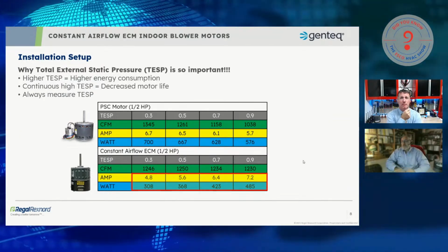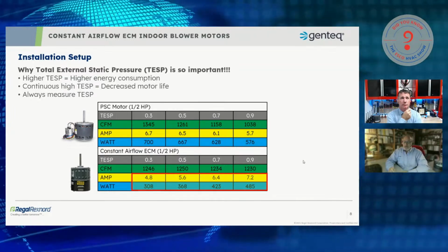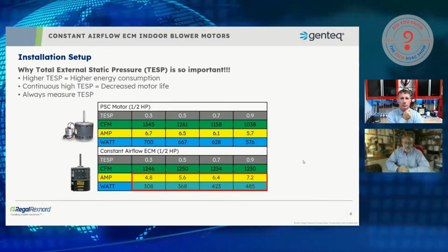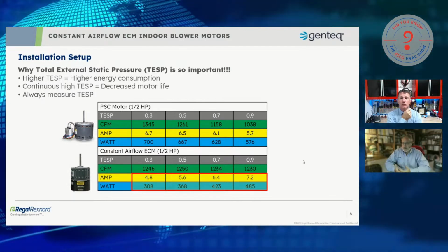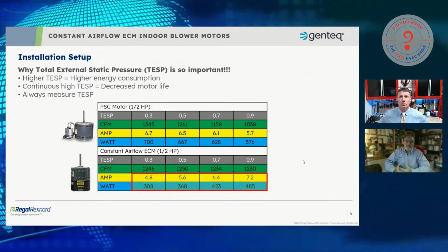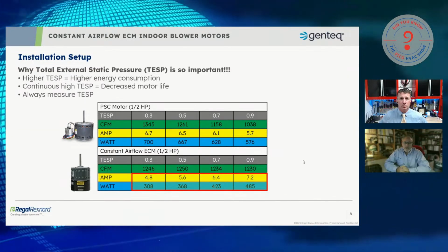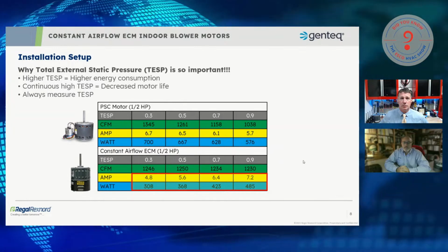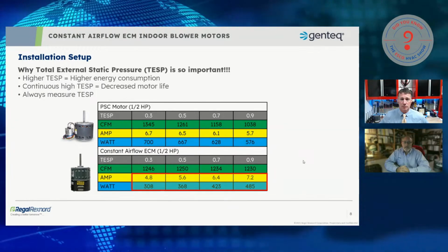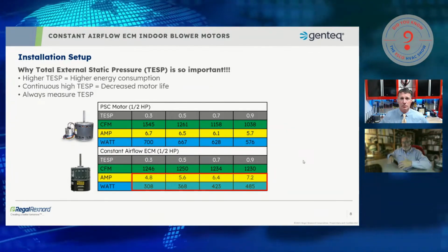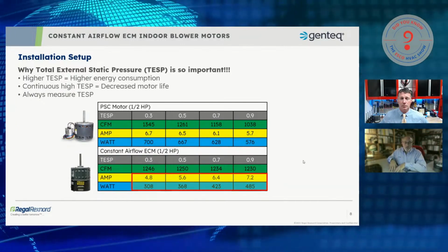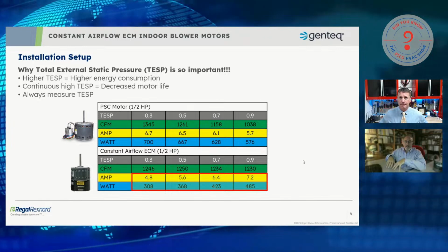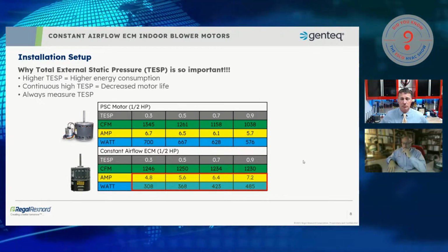And it's funny, because technicians would often say to me, well, I don't know what the static pressure of an existing ductwork is when I install a new system. So how can I tell the customer until after I install the system whether they're going to need upgrades? And I actually had a couple of contractors tell me that they build that into their estimate. If the system they're replacing has a working motor, they would run that motor, measure the static, and then recommend ductwork based on the static pressure.